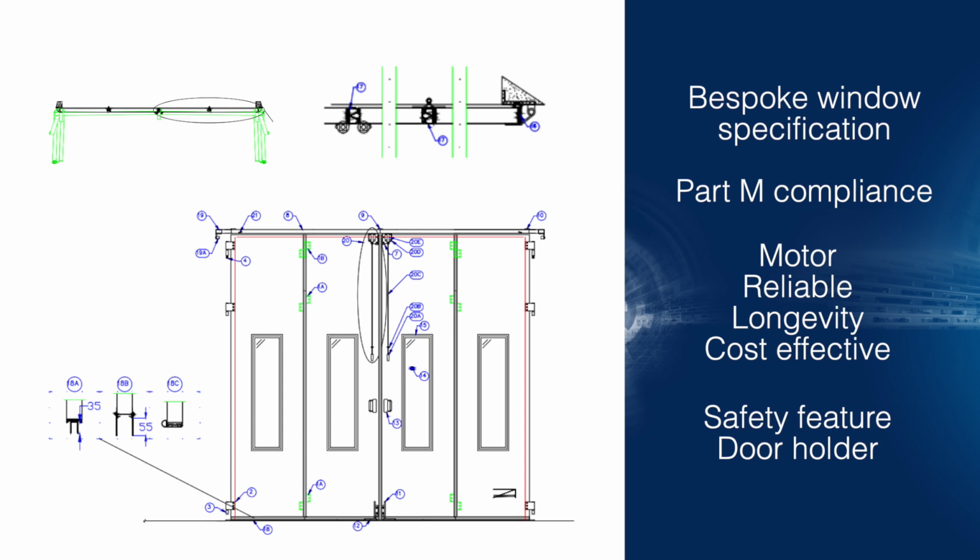Inward opening doors, on the other hand, can be equipped with a gas spring-controlled door holder featuring a semi-automatic opening mechanism. Once the set time limit is reached, the door holder deactivates, enabling the door to close automatically, without the need for any special actions. Electric doors will self-hold open when required.